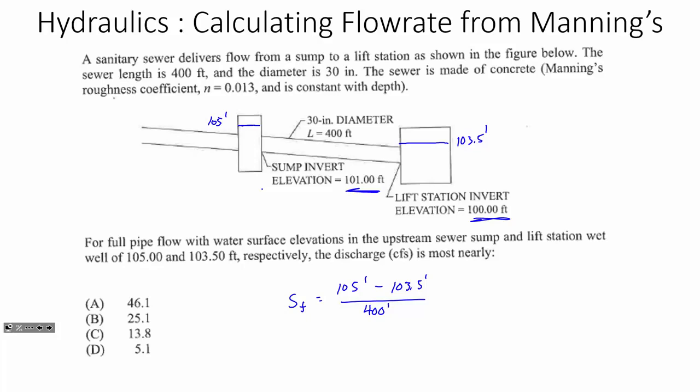So they don't crush you if you mess that up. But the correct slope here is going to be based off that water surface elevation in those two compartments. Okay, so this is a common theme. I've seen this occur again on that next problem that we're going to work with the Hazen-Williams equation. But very important here, you're using friction slope.